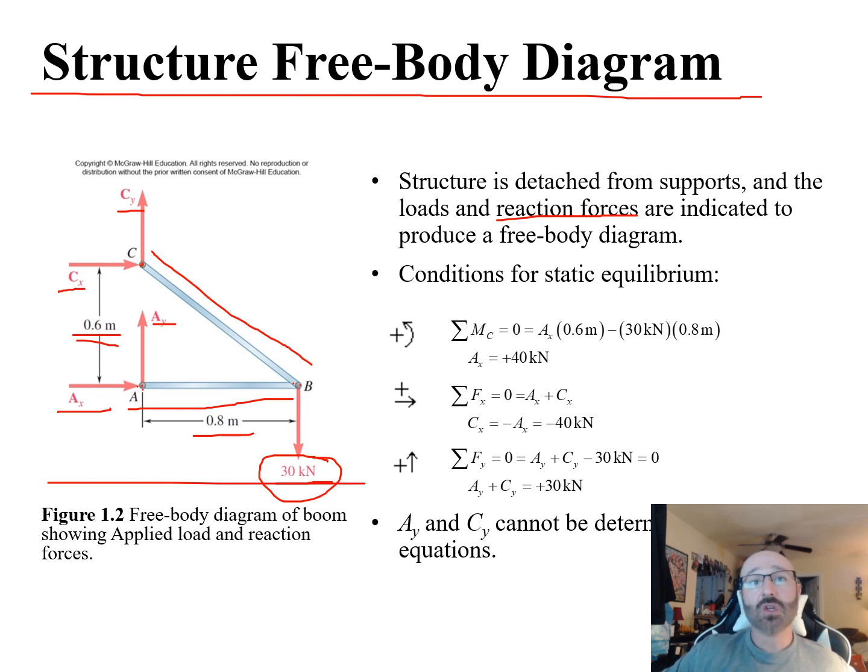So now what we can do is take a look at our summation of moments and our summation of forces. And we recall that from our statics courses as well. So we can say, okay, we can do moments about a couple different areas. Let's just take here and say, let's do our moments about C right here. So we can go through, figure out what are our moments about C. And we recall for moments, it's going to be our forces times perpendicular distance.